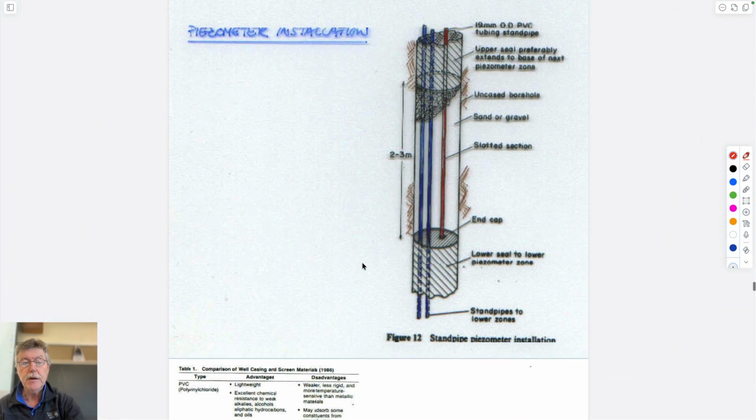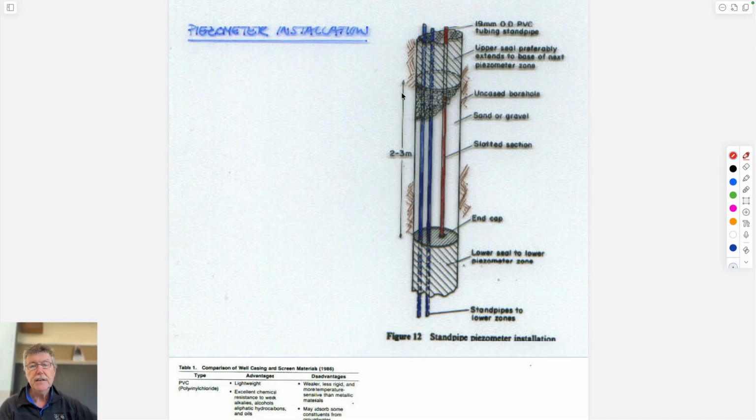The kind of piezometers we just talked about are like these. These are standpipe piezometers. So the idea here is this is your empty drill hole that goes down to whatever depth. You put in that empty drill hole one of these pipes, a piece of 1-inch PVC pipe that has slots cut in the end to let water in. You push it down to the very bottom of your hole, and then you dump down the borehole a whole bunch of sand, so it sits in a pad of sand.